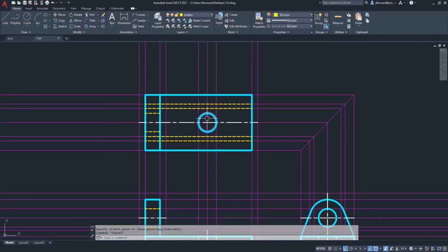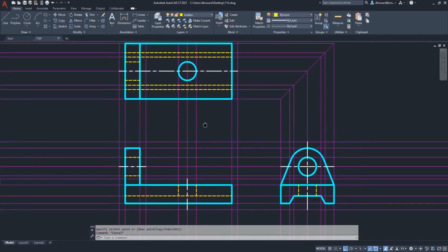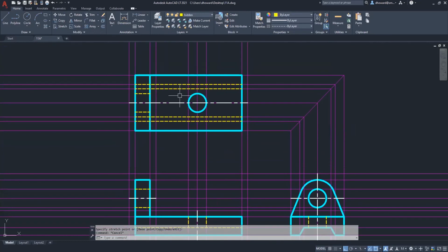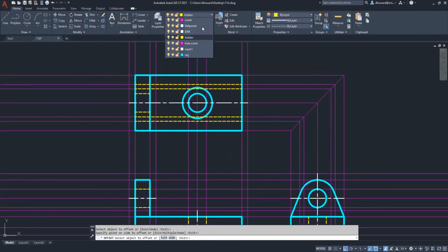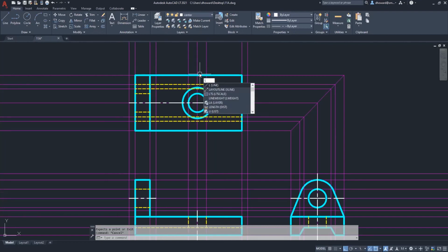And then I also need a center line going through the circle here. I need it to be 1/4 of an inch away. An easy way to do that is just to offset the circle temporarily. So if I do that, and then I go to my center line, man, it is struggling to stay. Click there and then click there.